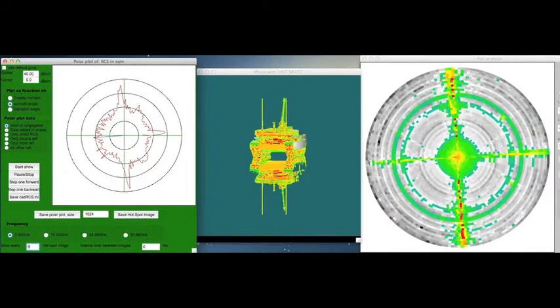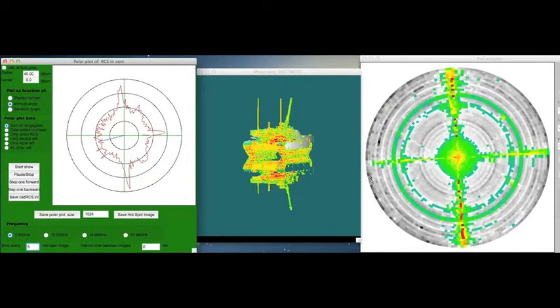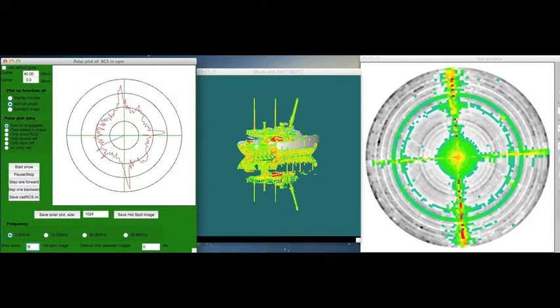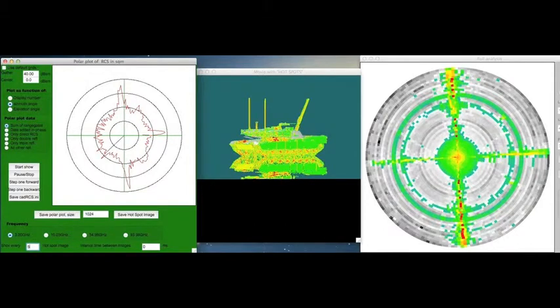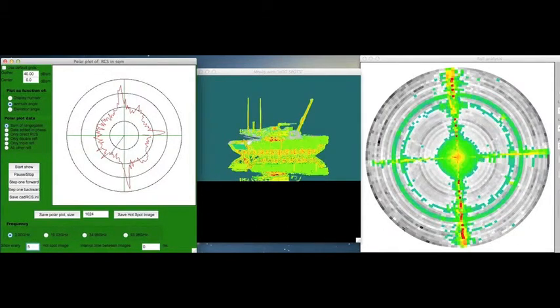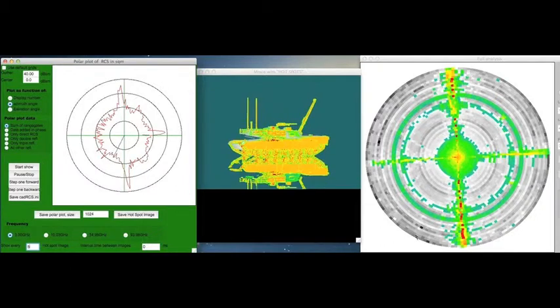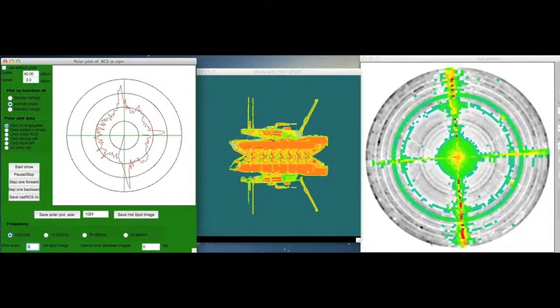With cadRCS you can do simultaneous calculation of 4 frequencies at the same time. You can also have 2 receivers at the same time, but only one transmitter. If you need to have a calculation with another transmitter, you need to run the calculation again.